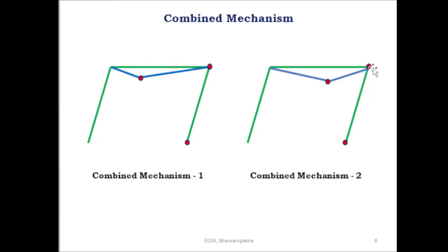Here you have to take the plastic hinge at C and D, and another plastic hinge under this load. There is no plastic hinge at B, and you have to take the mechanical hinge at the support A. Here there is no plastic hinge. So these are the different mechanisms when both ends of the support are fixed and when one end is fixed and the other end is hinged.